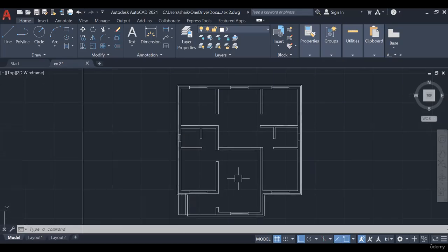Okay, I just quickly draw the slab projection. What is slab projection? From the face of the wall, how much it comes outside. Why do we need to provide the slab projection? To avoid dampness of the wall in the rainy season. In areas with heavy rains, we need to provide the slab projection so that rainwater does not directly enter the wall. So there are fewer chances of dampness of the walls. For that purpose we are providing the slab projection.